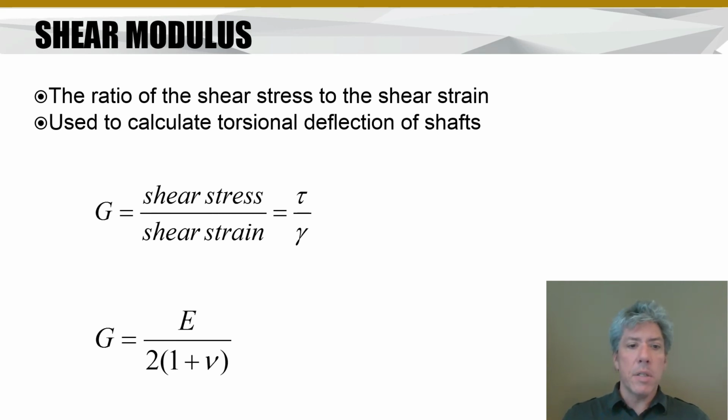However, there is actually a relationship between the shear modulus and, well, I'll call it Young's modulus, the elastic modulus. The shear modulus can be calculated from the elastic modulus, and vice versa, as long as you know Poisson's ratio. Now, that's the right symbol for Poisson's ratio. I think it's actually called nu. It's actually a Greek symbol. You can call it V if you want. That's actually the relationship between the shear modulus and the elastic modulus.